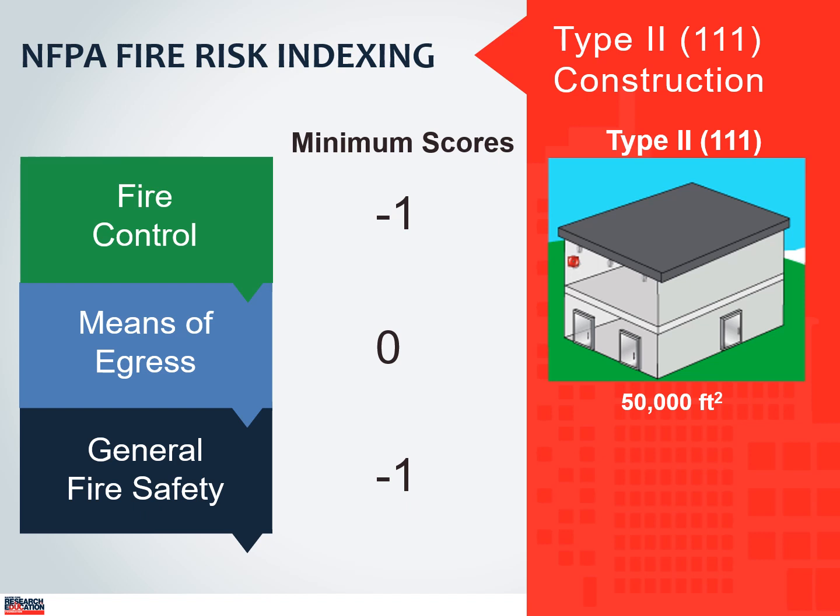In this building, with a construction type of unrated combustible, its construction score is -1. If its stairs are not enclosed, the score for vertical openings is a -2. These two items alone would cause the building to fail. The score would be a -3, and the mandatory minimum requirement is -1. So mitigation measures must be considered.